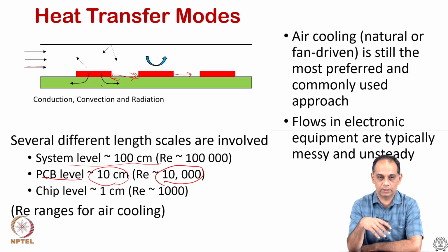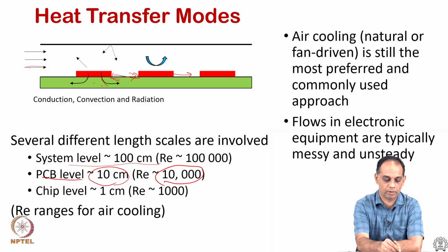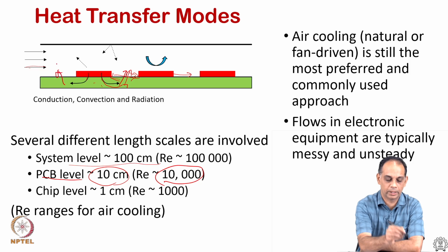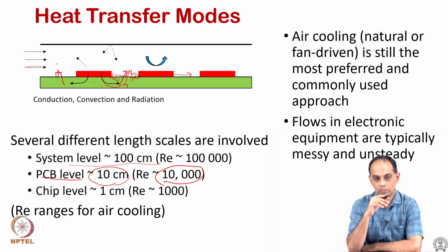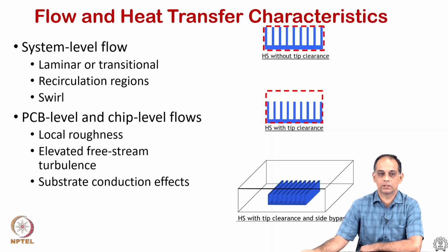All 3 effects are encountered because heat will be conducted from the package to the board, and heat can be dissipated from the board itself to the incoming air. So, how do I work? What heat transfer coefficient should I use is the question that we always encounter.